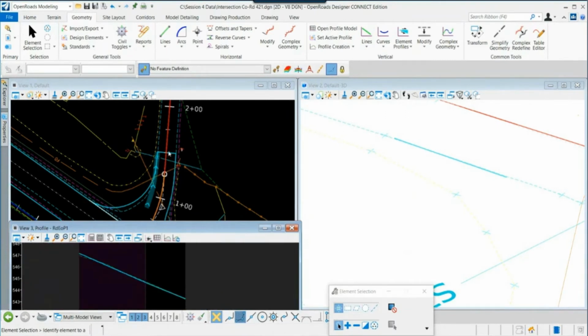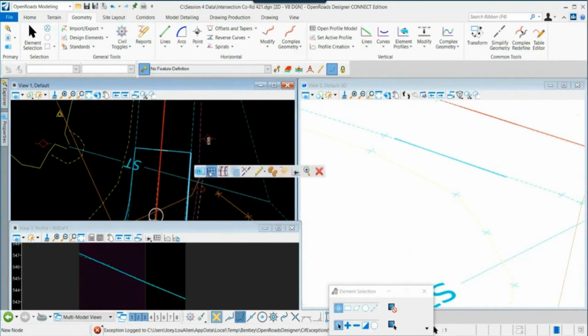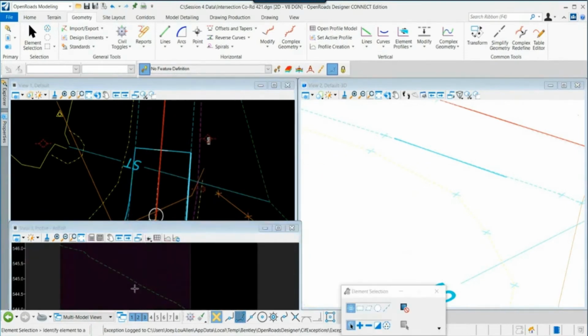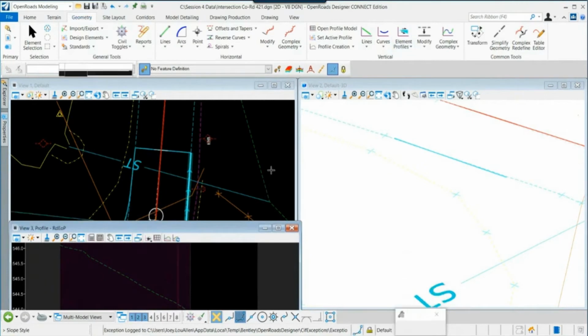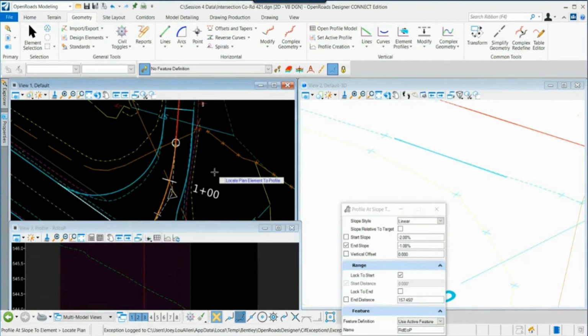So we've defined the profile on the western side. Let's follow the same process and modify the profile on the opposite side. So let's look at the profile view for that side. Again, I'm going to use the same command, go through the same process. I'll data point, locate the element we want to profile. The reference element is back to the baseline. Again, I'm just going to pull the cursor. I'm going to go the entire element. So I'm going to assign that. The final profile here, it's a little steeper on the cross slope, so I'm going to input 5% in data point.